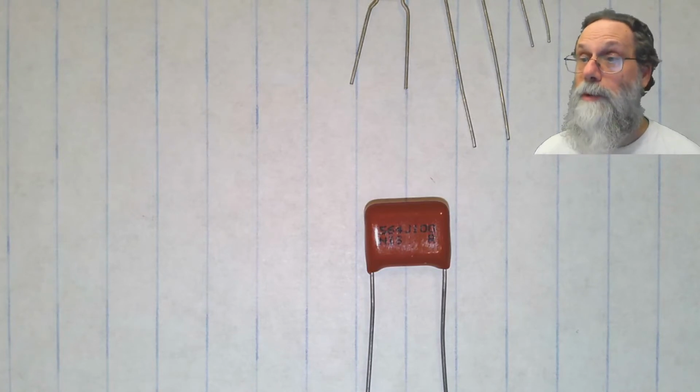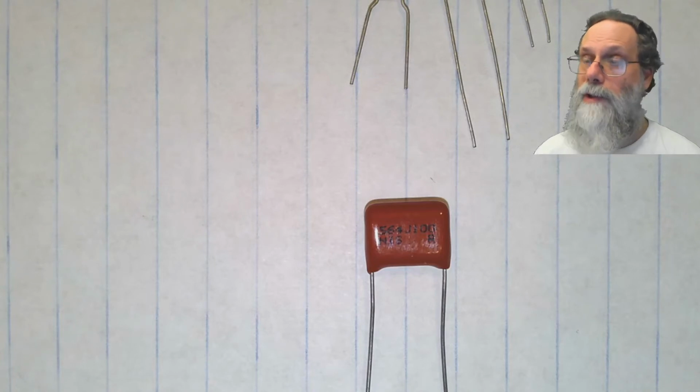Now, plus or minus 5% is actually pretty good for a capacitor. I mean, you can get capacitors that are more precise than that, but the cheap ceramic ones are never that precise. So that's what tells me this is probably not a ceramic capacitor. It's probably a film capacitor, having some sort of plastic film inside as the insulator instead of ceramic.